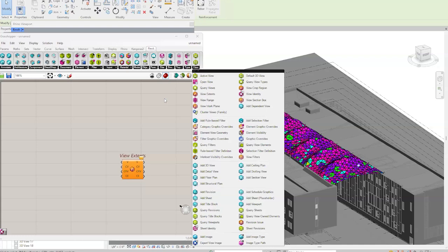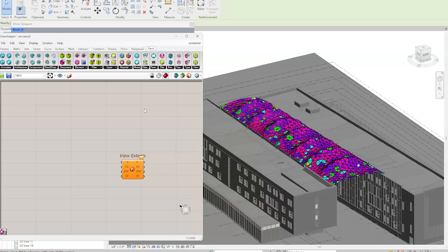It's the same thing with tolerances. Yes, we can do crazy geometry, but bringing it into Revit, it's always going to be subject to that small 0.01 of an inch tolerance. We handle the geometry really well. We'll try to bring it in as native Revit geometry. Then we have a series of import options that will end up in that mesh that you don't want. But we try to bring it in per Revit's geometry rules. If it doesn't meet those rules, we'll go to the next, looser version and so on.